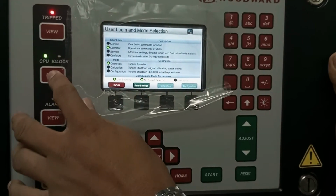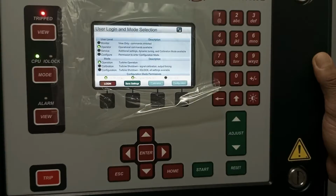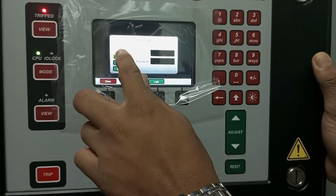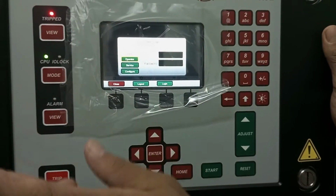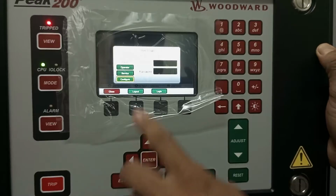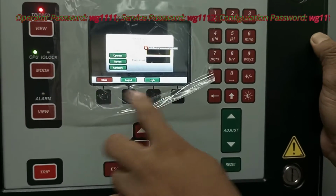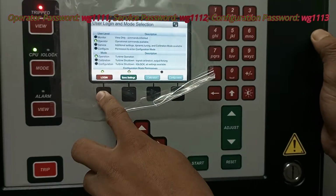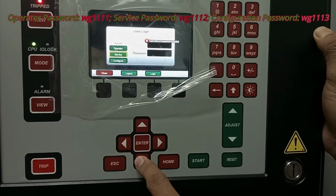So first we have to log in. Go to More, then go to the login option. In the login option, you see the operator mode, service mode, and configuration mode. As we want to configure this controller, we have to go to the configuration mode, then put in the password, so we can configure this controller as per our data sheet or required documents.